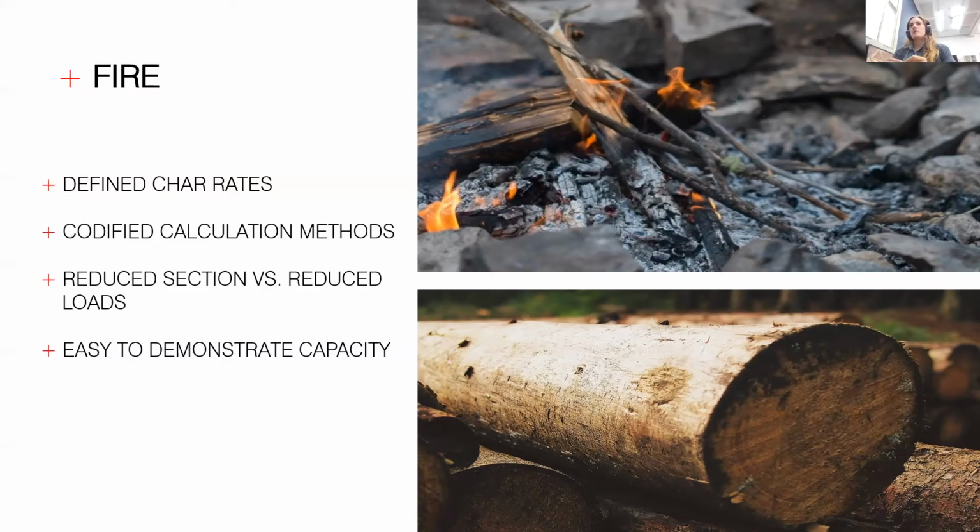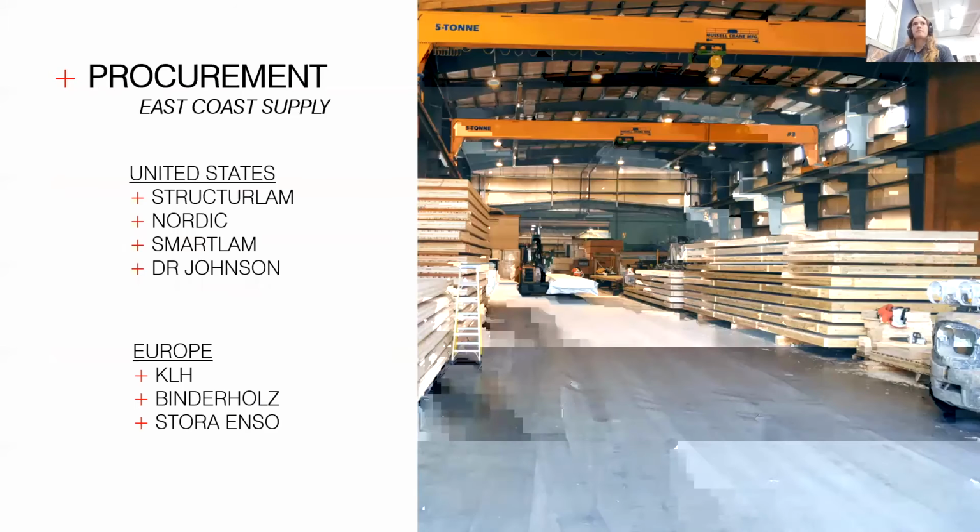The other thing that's important to understand is because we're talking about mass timber, it will burn more like a log and less like light frame construction, which is more like a kindling type of fire where things can burn much more quickly and easily and spread. There are also options for introducing sprinkler systems, which are requirements in some building types. And like I talked about, some requirements for encapsulation, which really just limits the fire load depending on the size of the building.